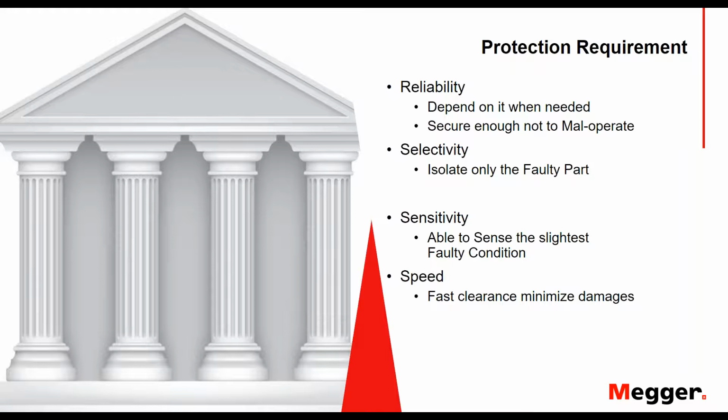Now, even with having dependability on your relay, you should also have security, meaning during this whole long period of non-operation, if there is no fault, there should be no operation. What we call mal-operation should not happen when you have a reliable system.